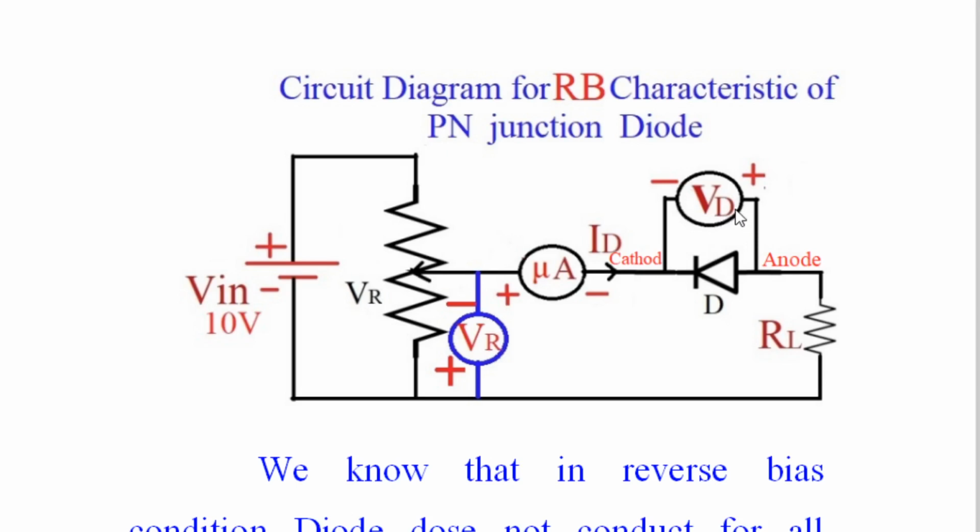In this way we are going to measure all these three parameters for various reverse voltages applied as input. And you'll observe that this voltmeter is connected in negative direction, and the current meter will also show the current in minus only, because this is reverse current.